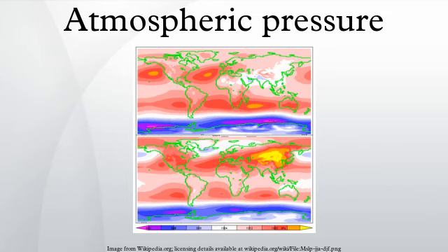QNH is the barometric altimeter setting that causes an altimeter to read airfield elevation when on the airfield. In ISA temperature conditions, the altimeter will read altitude above mean sea level in the vicinity of the airfield. QFE is the barometric altimeter setting that causes an altimeter to read zero when at the reference datum of a particular airfield. In ISA temperature conditions, the altimeter will read height above the airfield runway threshold in the vicinity of the airfield. QFE and QNH are arbitrary Q codes rather than abbreviations, but the mnemonics nautical height and field elevation are often used by pilots to distinguish them.